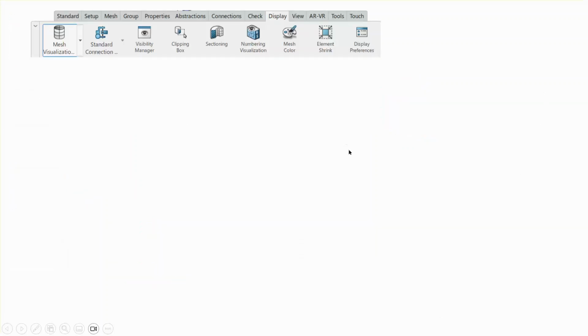The other thing is that when you create beams in space, basically they're straight lines, okay? The cross section is defined by the shape and everything, but you make a straight line, and then when you mesh it with beam elements, you have to tell it what the cross section looks like. That being the case, you can actually display it in 3 dimensions so that it gives you the impression that you're really doing a 3 dimensional problem, but you're not. It's just still beam elements.